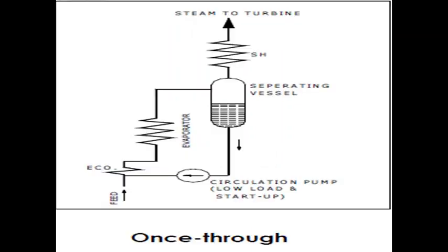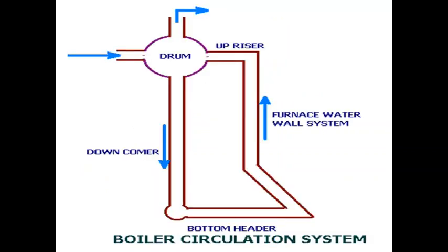So this recirculation continues when we are operating the supercritical units in subcritical regime, and as we go on increasing the pressure, gradually this separating device is bypassed and directly water is getting flashed into steam. So this way we find the implications of circulation exist so long as we operate in the subcritical regime of operating pressure.